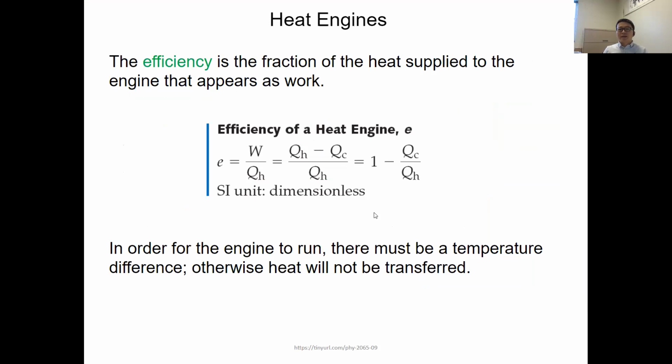Efficiency then is defined as the work done by the engine divided by the heat it takes in, so W over QH, and it can have two other forms, QH minus QC over QH, or 1 minus QC over QH, okay?